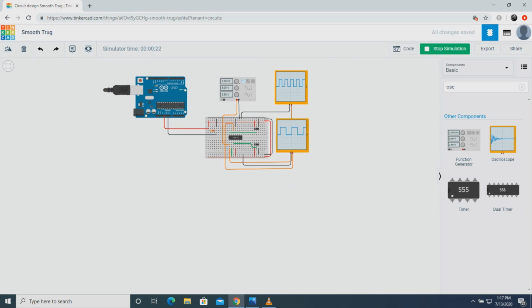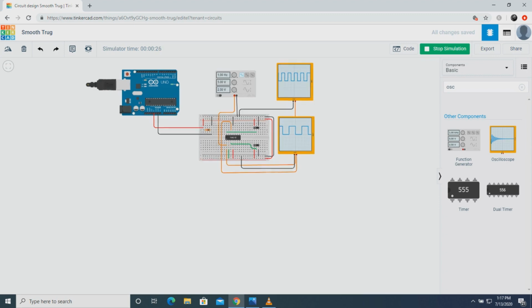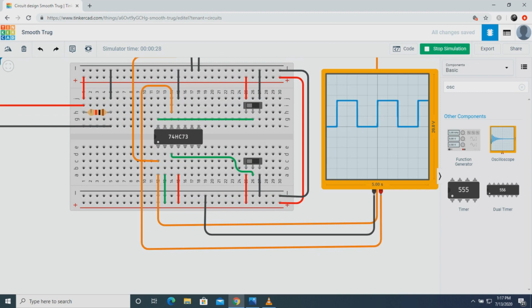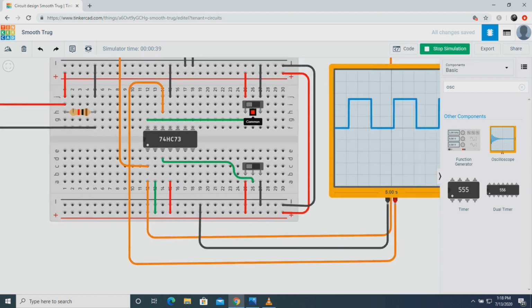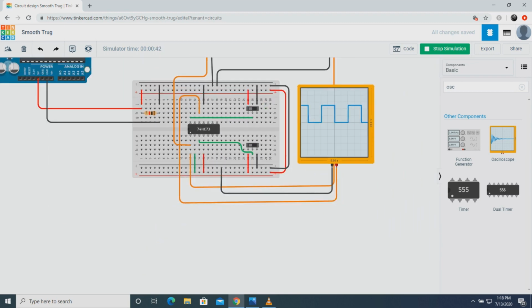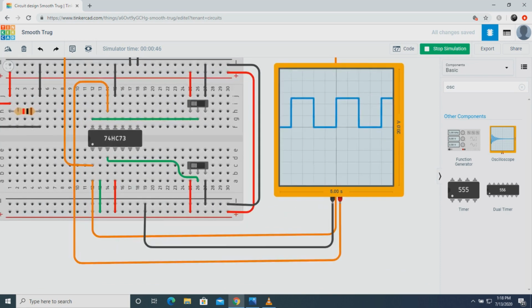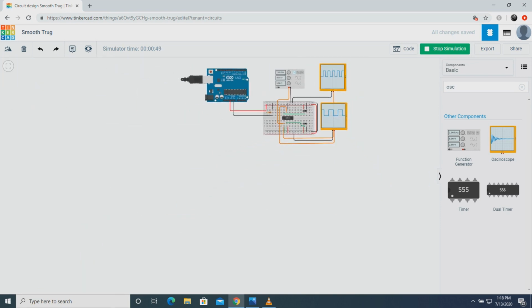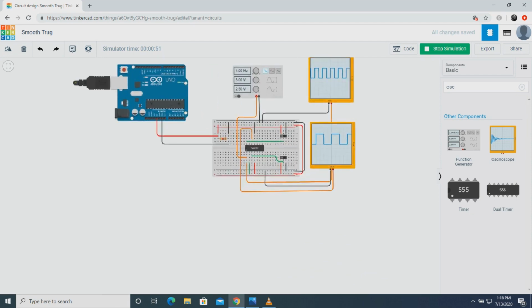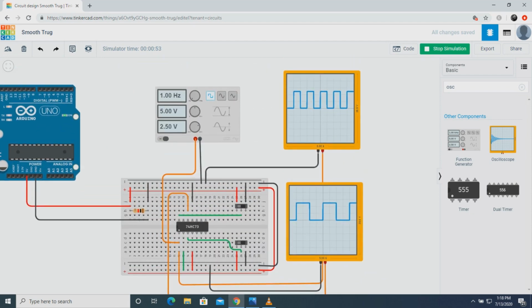So you can see here what's happening in these two nodes. This is our J and these are K, both connected to the VCC, so 1 and 1. When they are both 1, it will be in the toggling state. You'll see that the previous state 1, next is 0, then 1, then 0, then 1 and 0, based on the time. This is a level triggered toggling operation going on there.